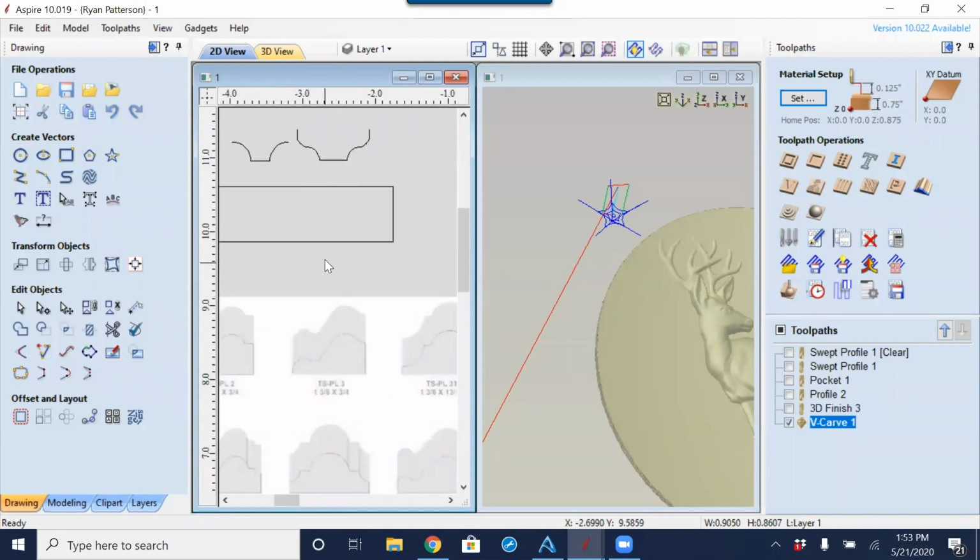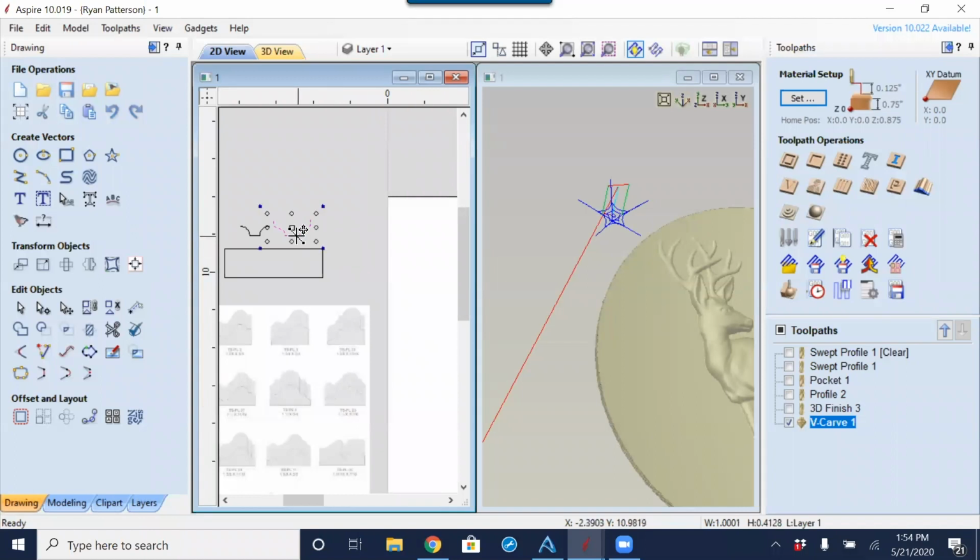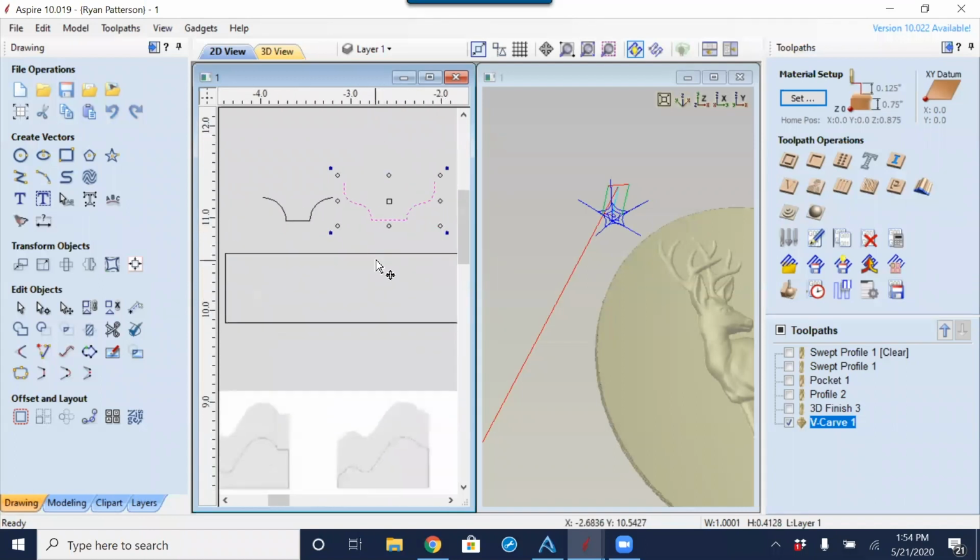So what we have now is, if we wanted to create much faster toolpathing, rather than doing this 3D type profile extruded, which could take some time to cut around here, we might have cutters or bits that are designed for doing profiled cutting. So I've drawn two of them out. You could buy cutters that have this type of profile. So you would just use a profile cut, either on the line or however you want to do it.